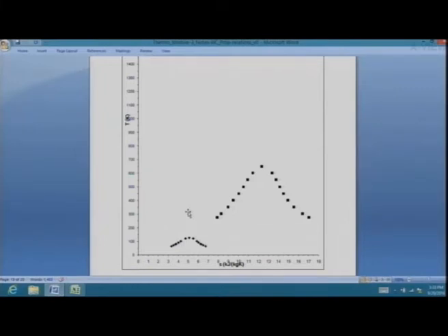So reduced temperature, the way we just defined a few minutes back, for ambient condition for nitrogen will be about 2. And so look, we are far away, and so we presume that air around us, and for all purposes of calculations and analysis, we treat air, or nitrogen part of air, as an ideal gas. Do the same thing for oxygen. The curve will be lower than this slightly, equally good for oxygen to be treated as an ideal gas at